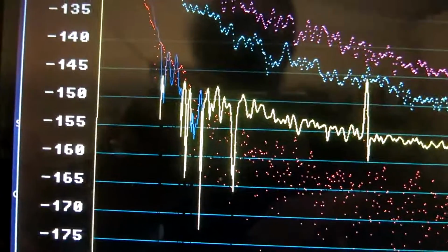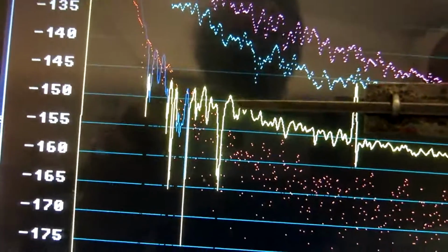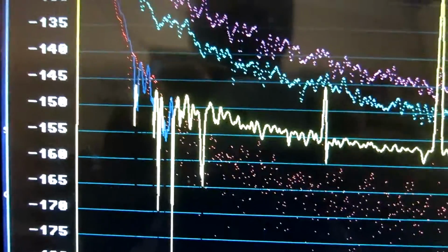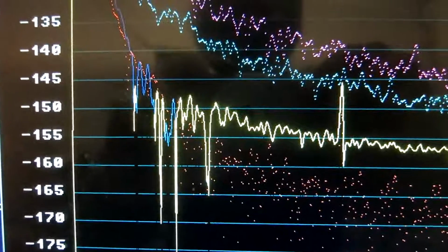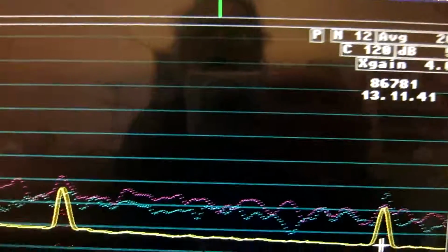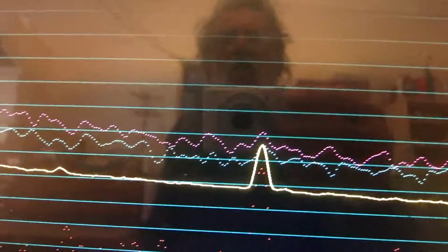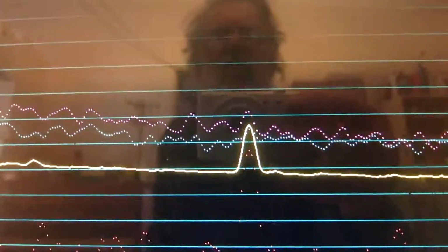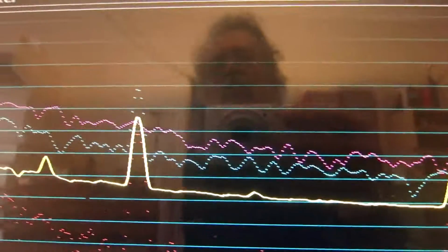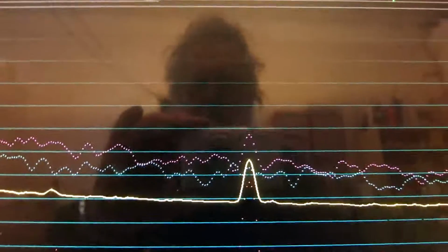It's now 12 hours, and I cannot read the performance at 20 hertz even with reasonable accuracy. So I would change the settings to make the resolution significantly lower. I have decreased the transform size by a factor of 4 and increased the frequency scale by a factor of 4. So peaks are much wider, and the time it takes to collect enough averages is shorter by a factor of 4.